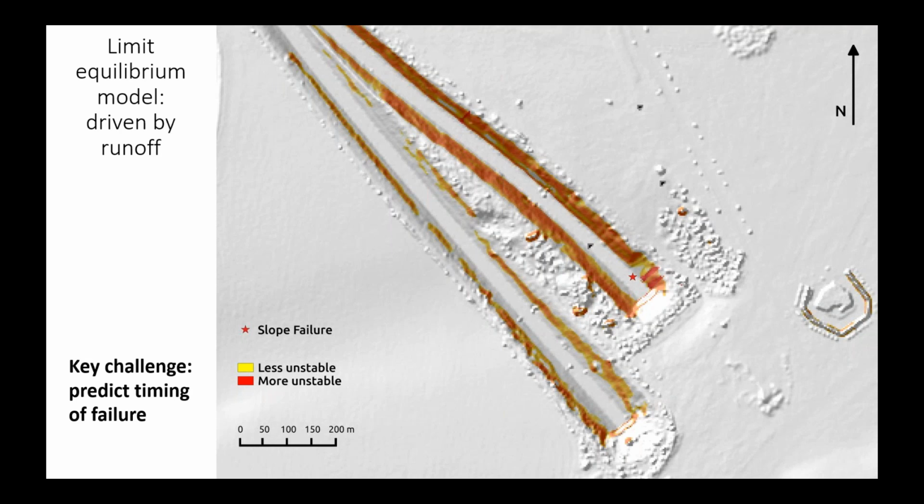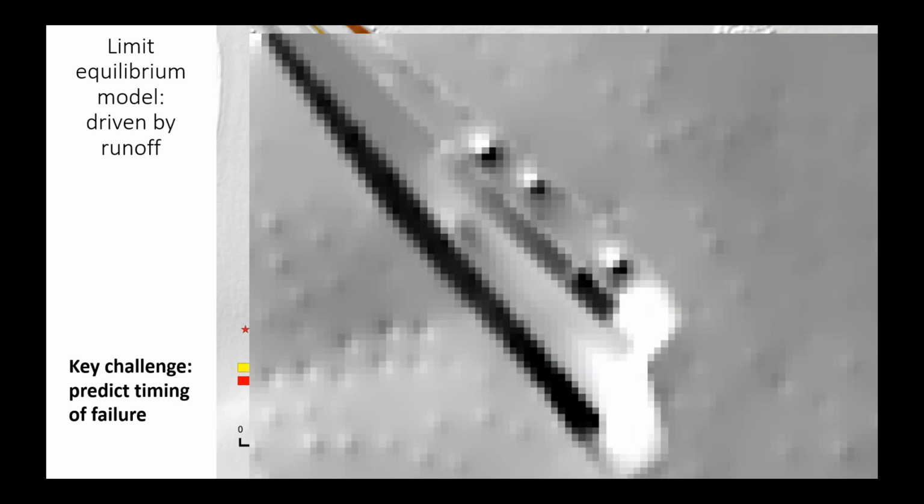If I look at the next map data, that's a 5-meter topographic data set that is our only current UK-wide high-resolution data set, although Ordnance Survey also has a 5-meter product. But those two products are not as high resolution as this, and I'll show you the same area at that resolution. This is what the 5-meter resolution looks like. And basically, it doesn't concentrate flow anywhere near that failure site. So really, we're quite restricted by our access to good topographic data.